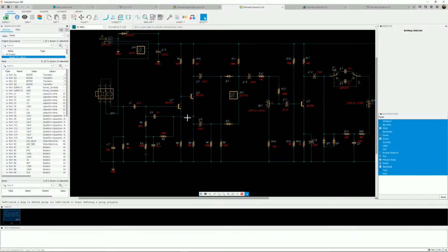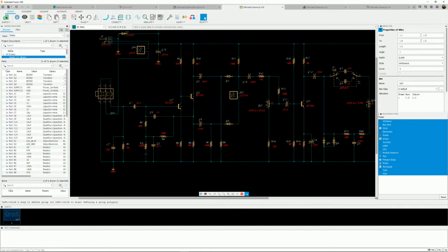So here, the DC voltage, it's a 2-transistor circuit, and the DC bias is incorporated into that. The first one's really just used as a buffer and a gain stage, so it's got fairly high gain, a little bit of emitter feedback there with the 1K resistor.